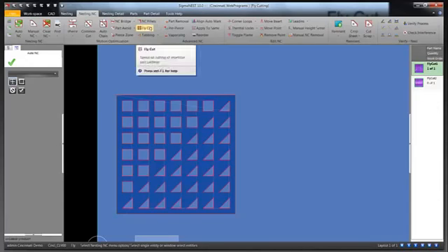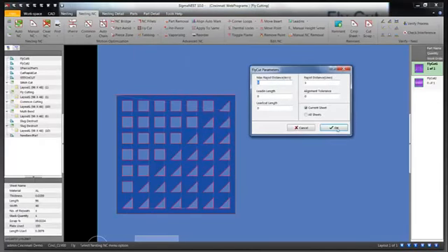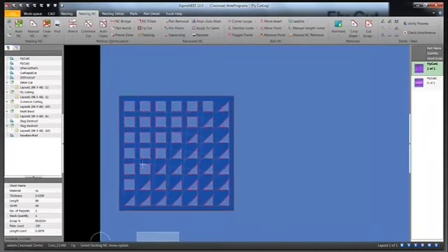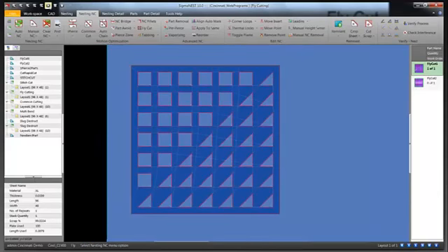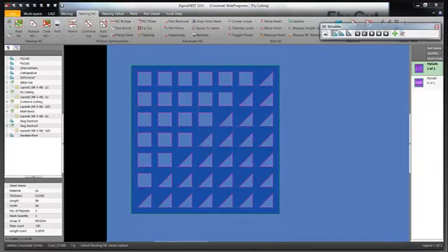So let's clear that off and put the fly cut on there. On fly cutting, when we simulate this, we're just going to go straight up to one side and down the other and propagate our tool path up and down the y-axis while we go through there. You're also going to see that it's going to take into account those diagonals while they go through here. And it does look at the geometry related to the next part as well.